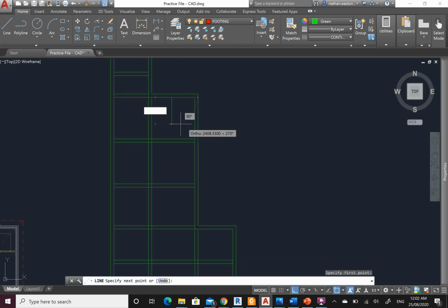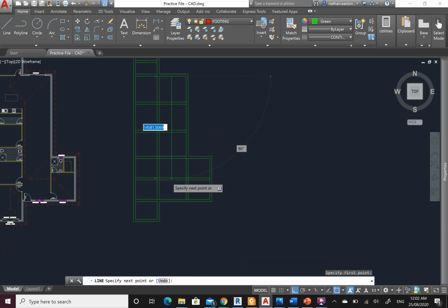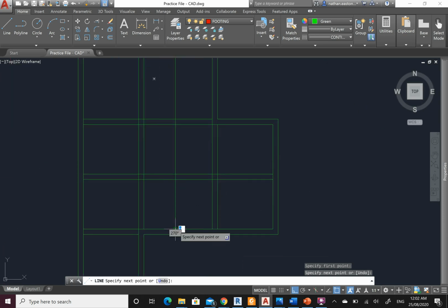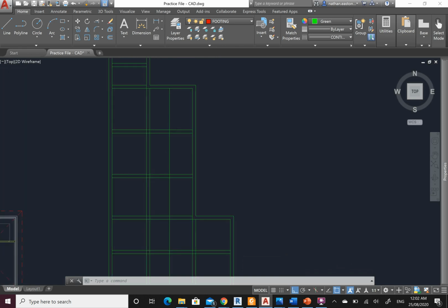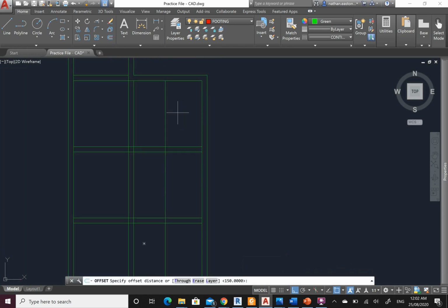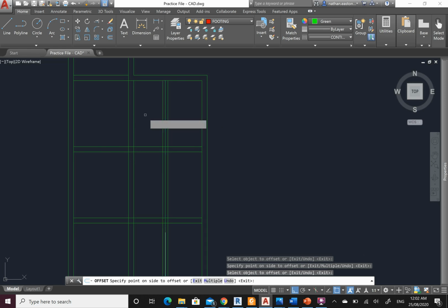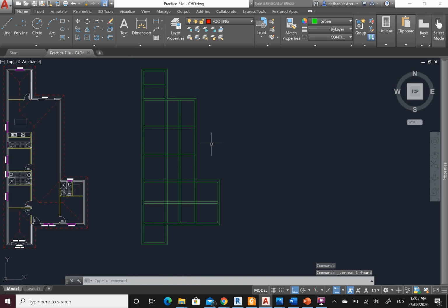Part of the standard is we can just come to here and put one into this grid, but I'm not really a big fan of it. For numerous reasons, which you'll discover when you study next semester, it's better to continue it the whole way through. It costs a bit more, but for the long-term effects, it's much better. So let's put one here and one here, and delete that one. All right. So that pretty much concludes our footing outline.